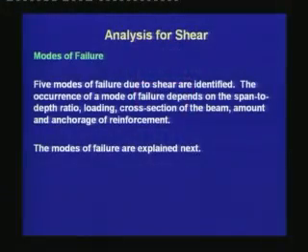Five modes of failure due to shear are identified. The occurrence of a mode of failure depends on the span to depth ratio, loading, cross section of the beam, amount and anchorage of reinforcement. The modes of failure are explained next.